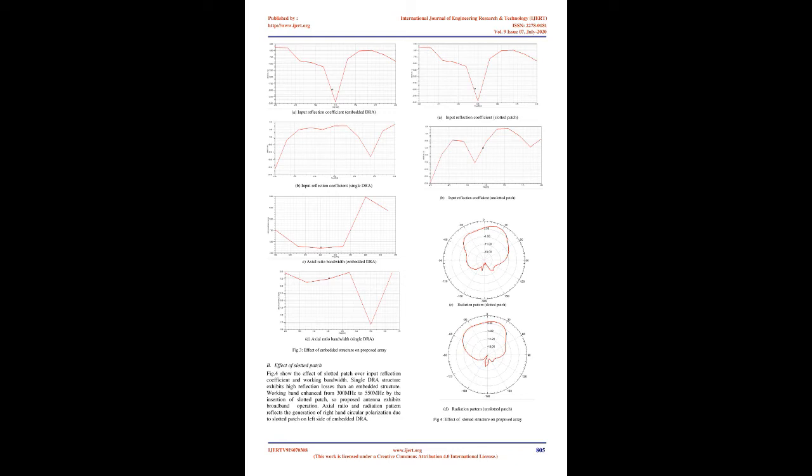Step 1. Designing of DRA with CPW feeding. A cylindrical structure is chosen since surface waves are less in quantity and it is easily modified. Here, we focus on HE11 mode excitation because we require circular polarization and CPW configuration of the mode. HE11 mode is composed of approximately 85% of TE11 mode and 15% of TM11. This mode is desirable for the most demanding applications due to its excellent radiation properties.